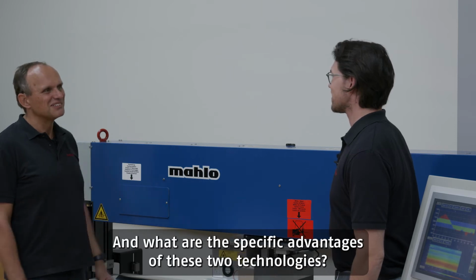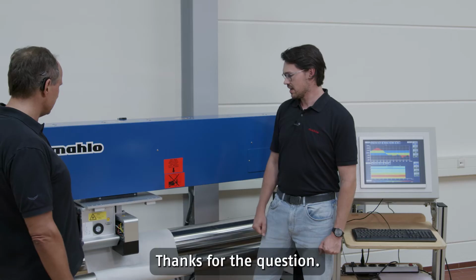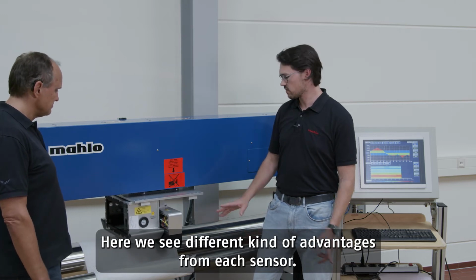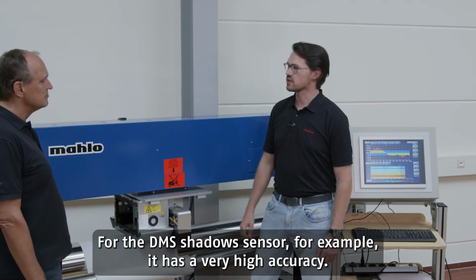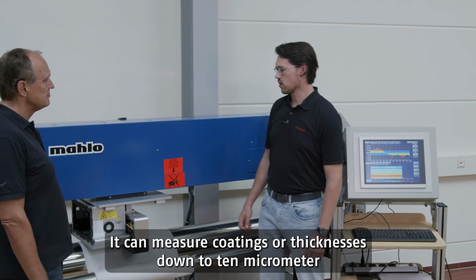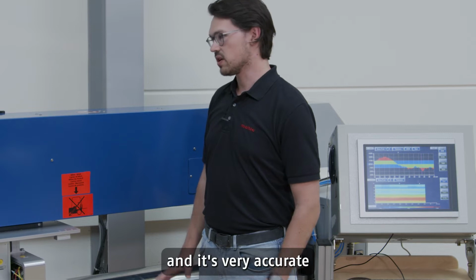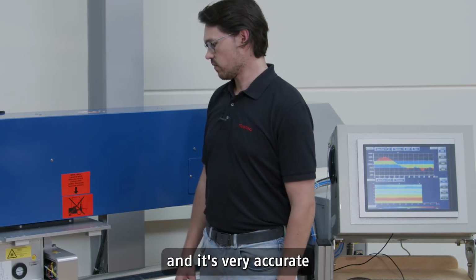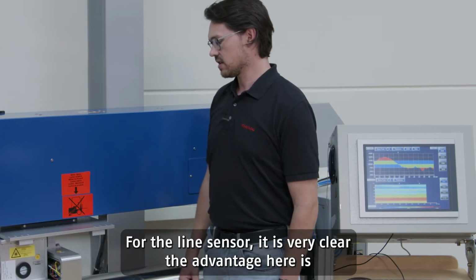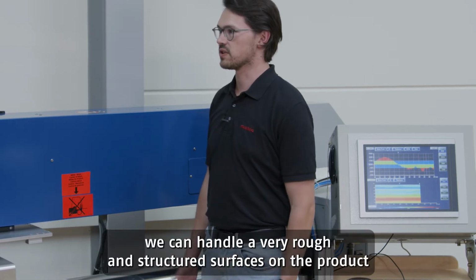And what are the specific advantages of these two technologies? Thanks for the question. Here we see different kind of advantages from each sensor. For the DMS shadow sensor, for example, it has a very high accuracy. It can measure coatings or thicknesses down to 10 micrometer and is very accurate depending on the product. For the line sensor, it is very clear the advantage here is we can handle very rough and structured surfaces on a product.